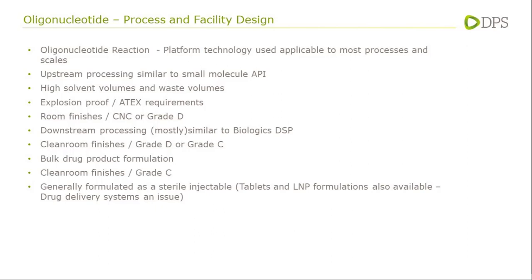Experience with handling these type of solvents may not be common in the biopharmaceutical industry, but the techniques required are commonplace elsewhere: tank farm design, solvent distribution and control, fire protection guidelines. Use of solvents like these carries an inherent risk due to their flammability and potential for explosion, so there are strict guidelines in place regarding handling, storage and the design of facilities used to process these materials.